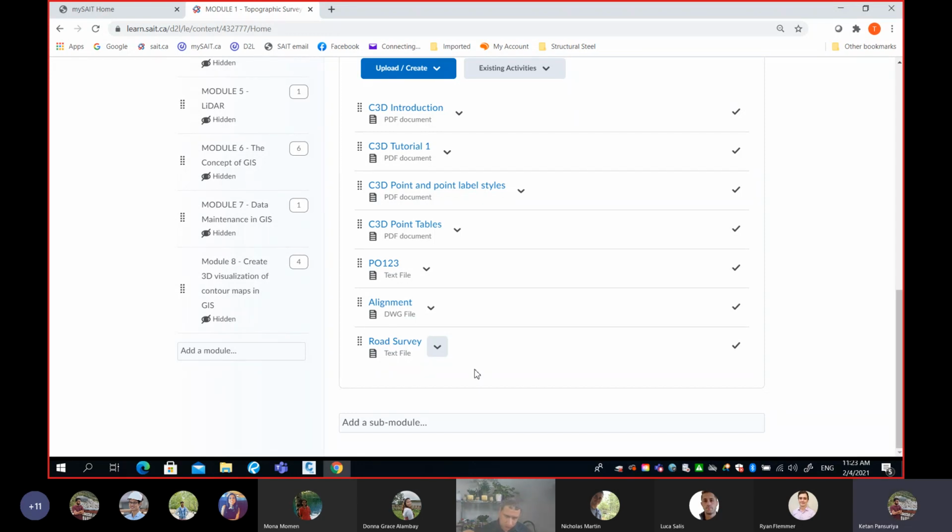What should be the second point after specifying the height of eye when you are checking the visibility? It's the point that you're trying to see or check the visibility to. So you choose the height of your eye, then the first point, then you input the target height, which, if you're looking straight at the ground, is going to be 0.